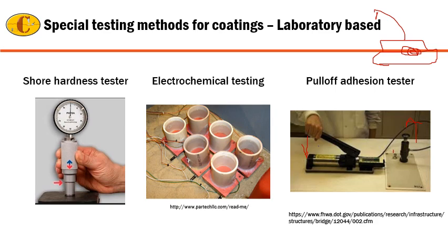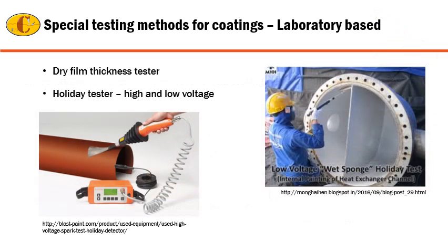The next is the thickness tester. So you have electromagnetic induction thickness testers which you keep on the top, and they are calibrated to the different thicknesses of the pipeline. So you can test what thickness is there on the pipeline or what was there previously.